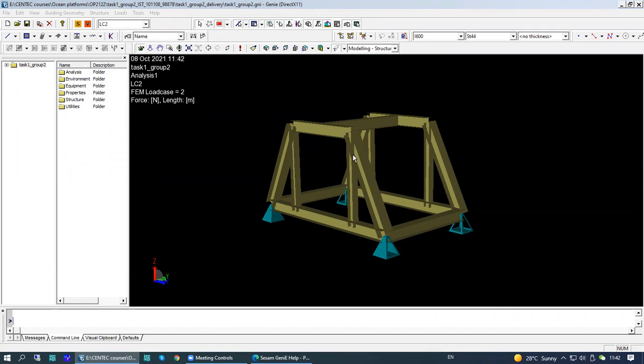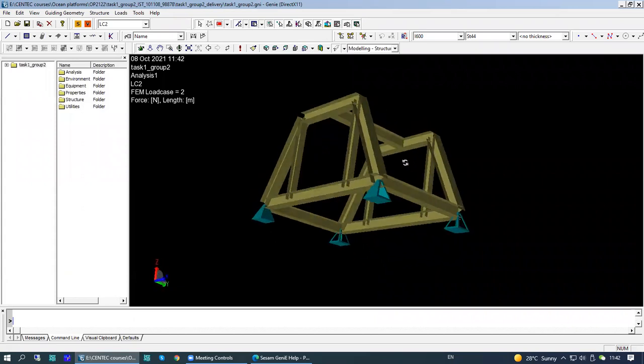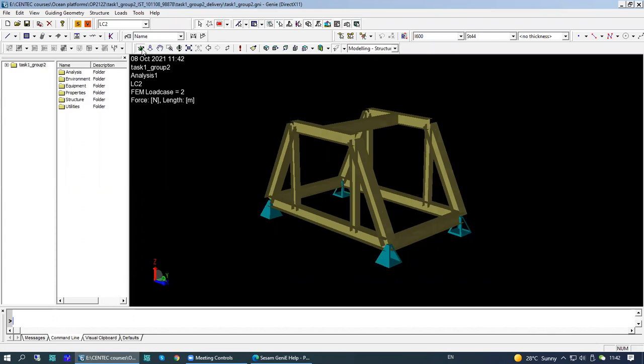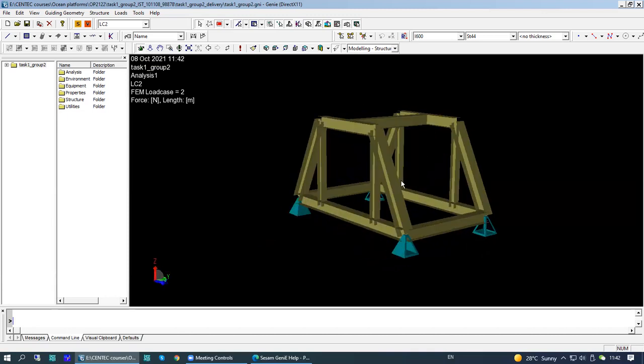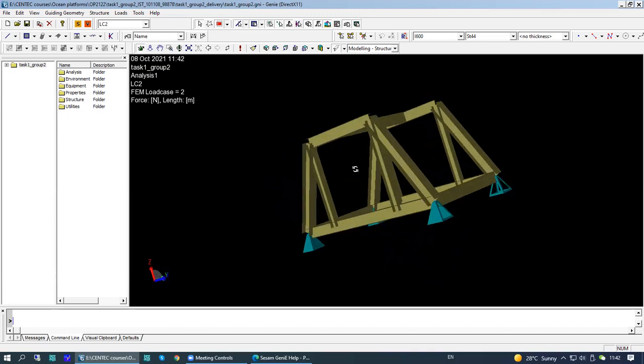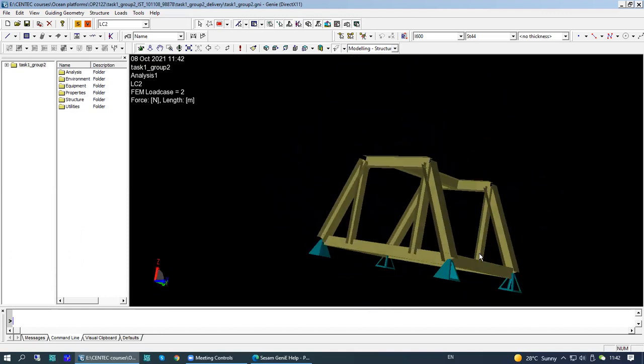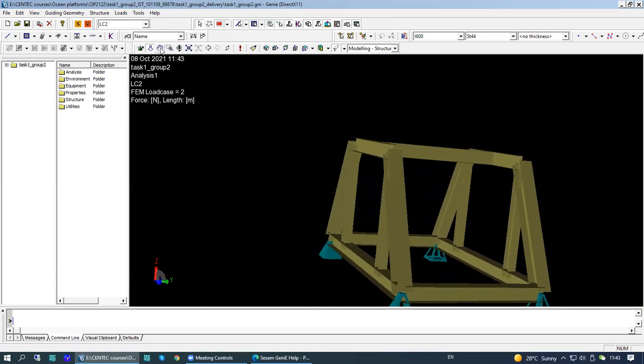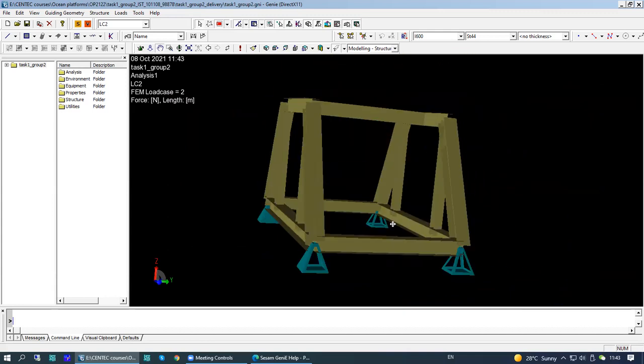Then, as I said, we have this example B1, and this is the whole structure there. So you see, I'm rotating the model now. How can I do that? You check this toolbar, you have rotate, zoom, and pan. Okay, so now this one is on. Rotate. You can use your right mouse button to rotate the model, around a rotation center. And you can zoom in, zoom out to make it big or small. You can pan it to move it left or right, up and down. Okay.